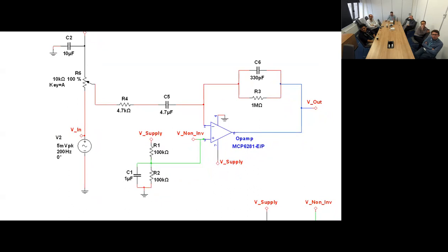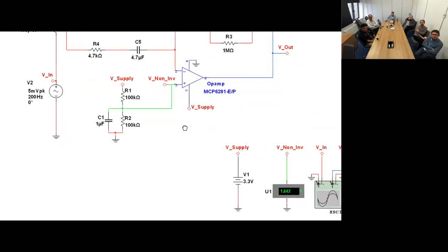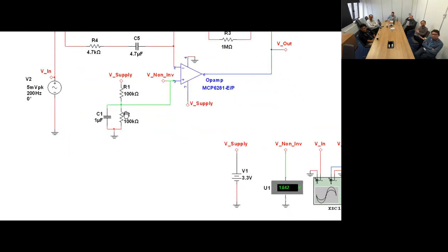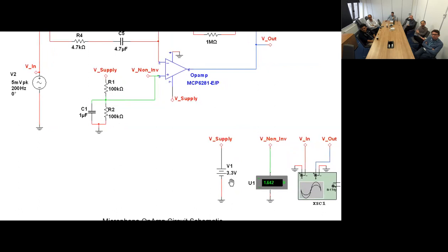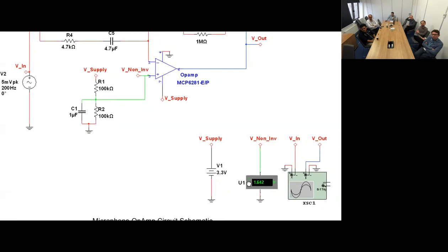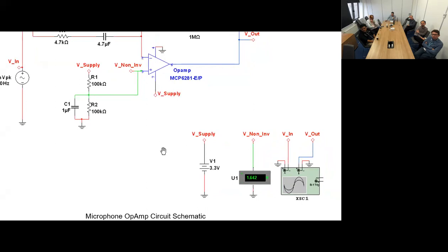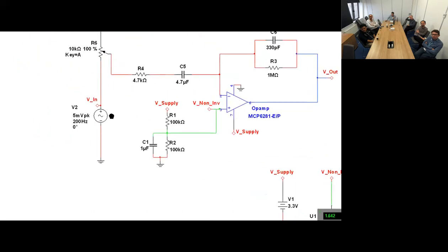And as we don't know how low the signal is going to be, it can also reduce the possibility of saturation due to a loud explosion signal. And here, another point is we are using a potential divider, which gives an offset of half of the Arduino supply voltage, just to minimize the possibility of clipping on the input signal.